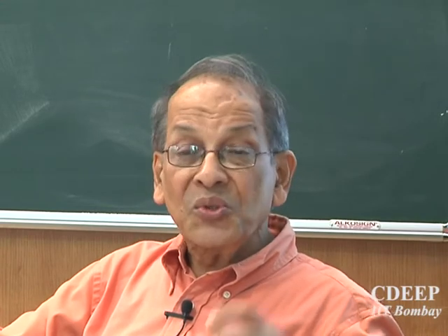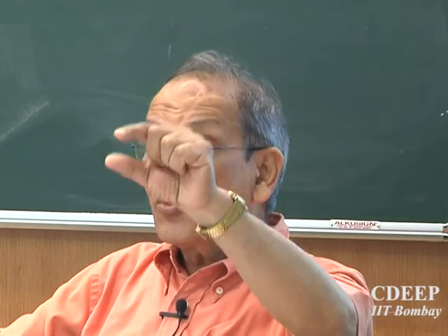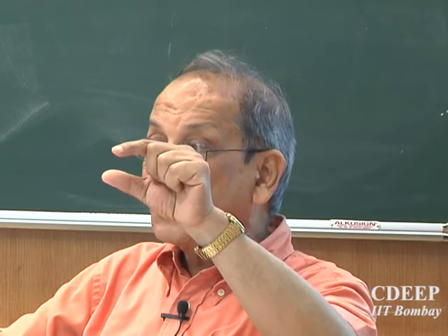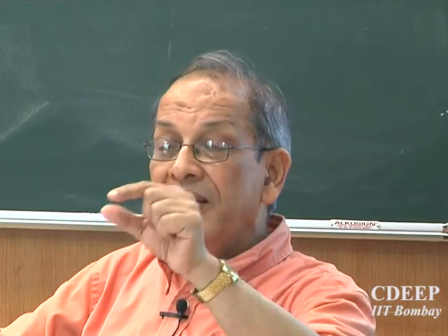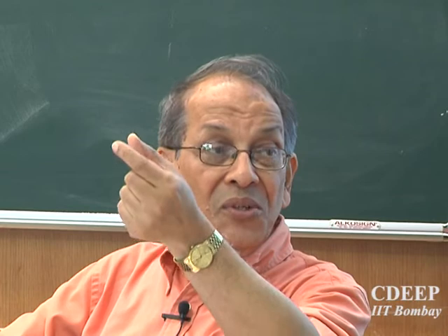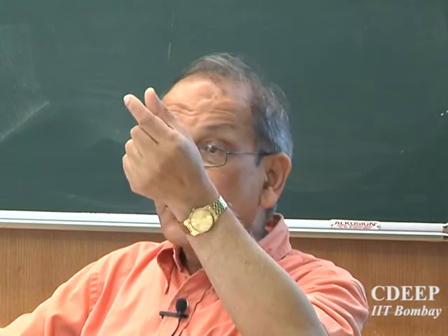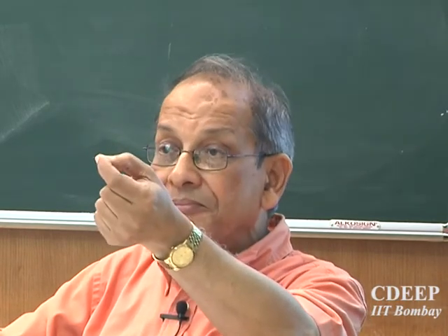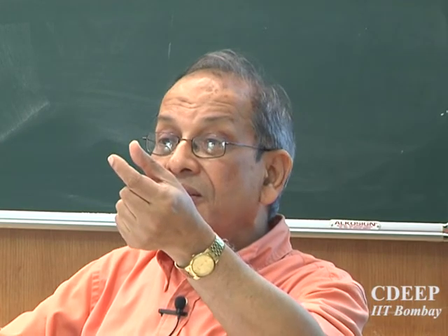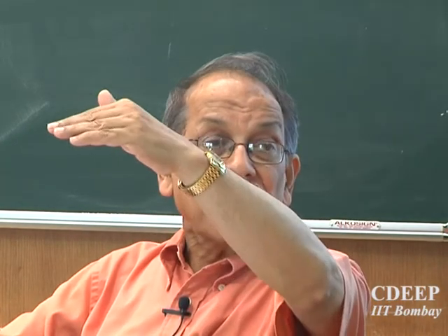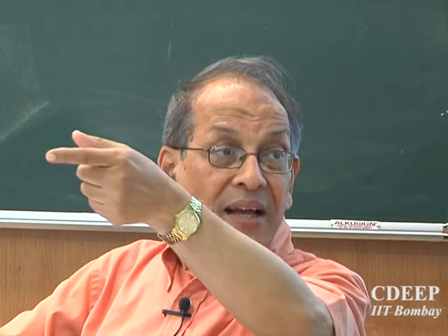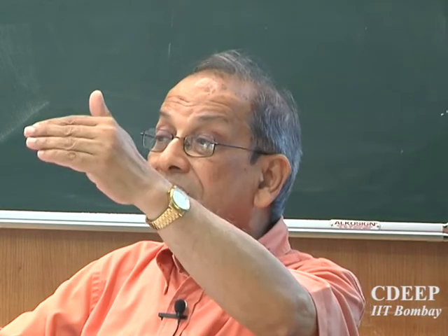So there are three principles: one is equilibrium, second is study of deformation, where you define strains and relate strains to displacement, and third, from forces at any cross section you get stresses, and from deformation you have got strains.